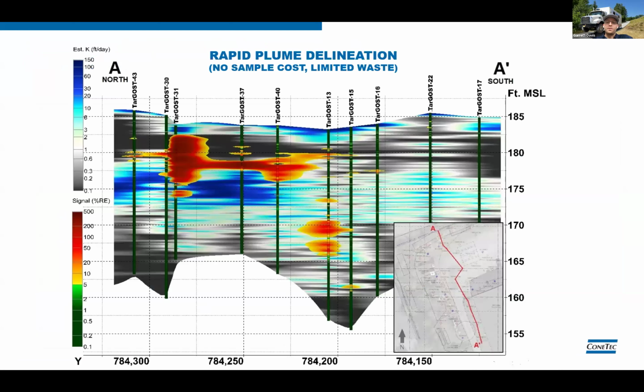So performing multiple soundings across a site provides the ability to map out your contamination plume from source to extent. And obtaining an understanding of the soil conductance and permeability along with the contaminant information allows the user to know if the VOC contamination is near a prominent migration pathway or not, or if it's bound up in a storage zone. This all aids in how the investigator should approach site remedial efforts.